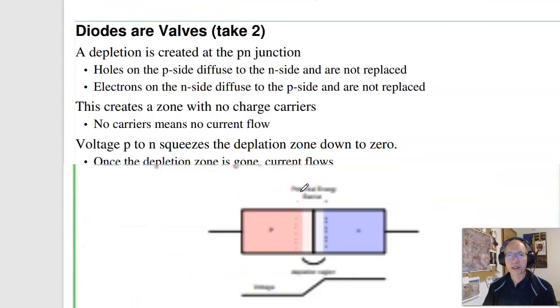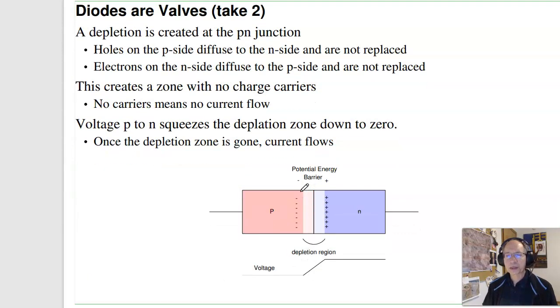That's one description. Another description. Inside the p-type region, I have Brownian motion. Some holes go left, some go right, and they kind of cancel out, except at this p-n junction. At this p-n junction, some holes go right, and there just aren't any holes to replace them. So the net result is all these holes over here get swept away and wind up on the n side.